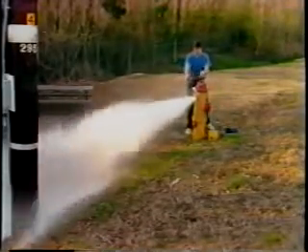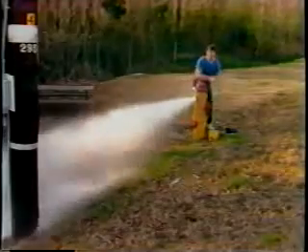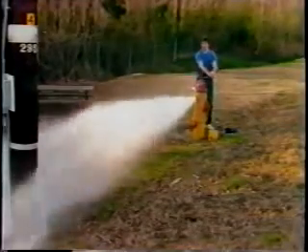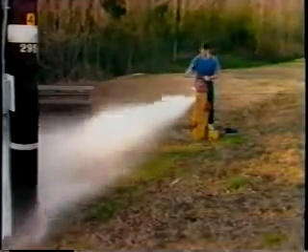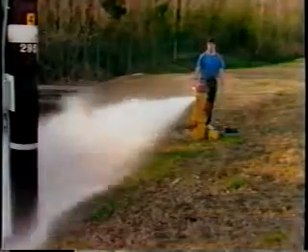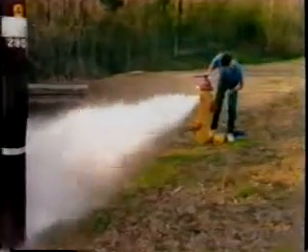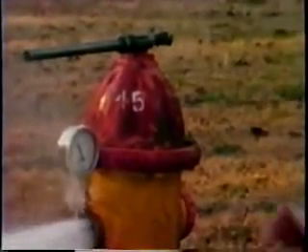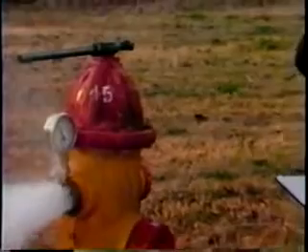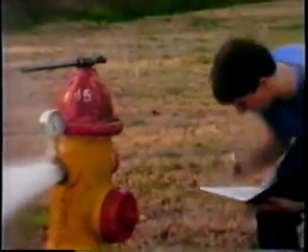Once the hydrant is completely open, the individual at the float hydrant will take a reading of the flow, which actually is a reading of the pressure head on the pitot gauge. Once he takes this reading, he radios it back to the person at the residual hydrant who will record it. It's also safe for the person at the float hydrant to write down the reading as well.